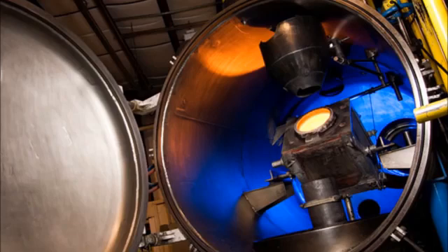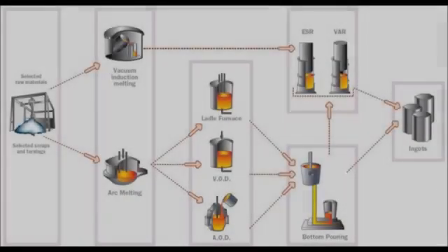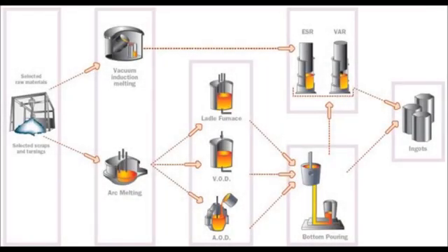This process continued for about 5 years, until, in 1958, vacuum arc remelting, or VAR, produced large forgings for discs, shafts, bolts, and structures, such as a turbine blade. VAR goes through the same VIM process, but then remelts a portion of the material and cools the material at a controlled rate.